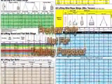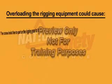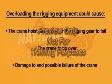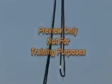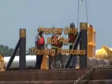Overloading the rigging equipment could cause the crane hoist line to part or the rigging gear to fail, the crane to tip over, damage to and possible failure of the crane. When not in use, rigging equipment should be removed from the immediate work area so as not to present a hazard to employees.